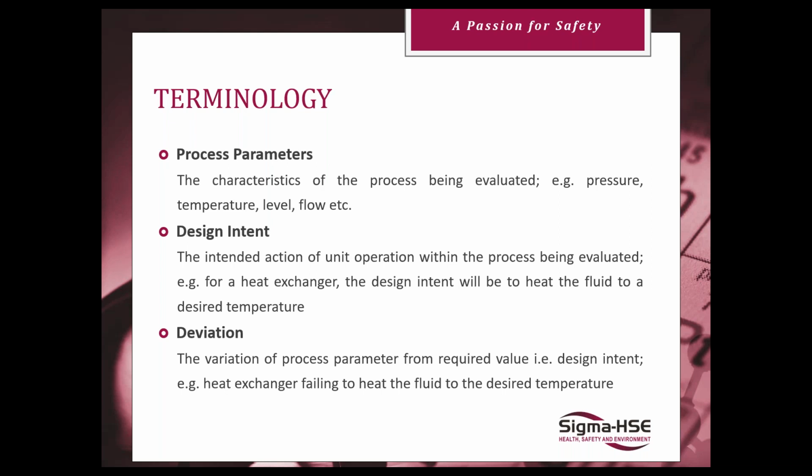All right, so process parameters: you look at your different parameters within the study. So if you've got a reactor vessel, you're looking at pressure concerns, temperature concerns, level concerns, reaction speed concerns. And then you're looking at the design intent. What is that unit supposed to be doing? Is it a heat exchanger? Is it just simply a transfer pipe? Is it a storage vessel? Is it a reactor? Is it a vent stack? What is the intent of design here, and what happens if it isn't?